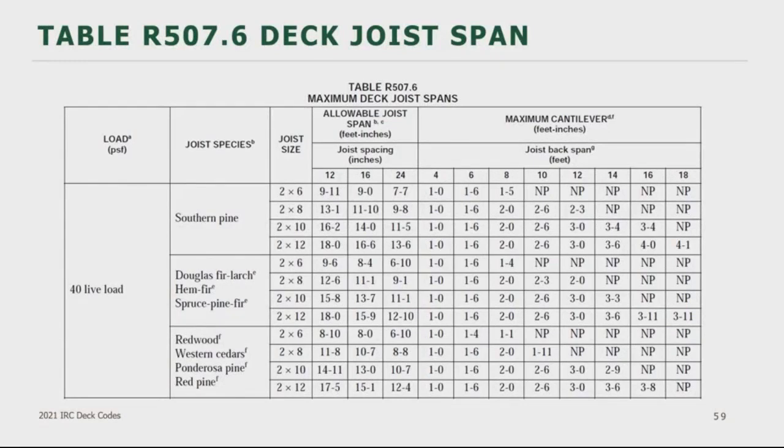There is nothing in this table about effective joist span length, so don't worry about that. This is actual joist span length. The effective joist span length is only used in the beam tables.